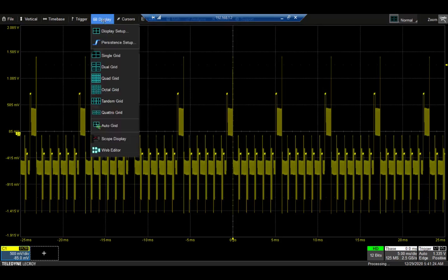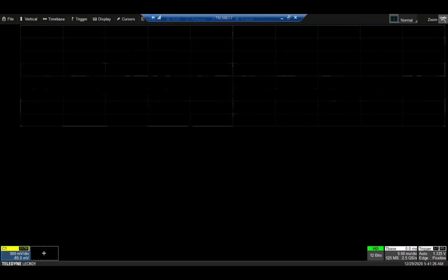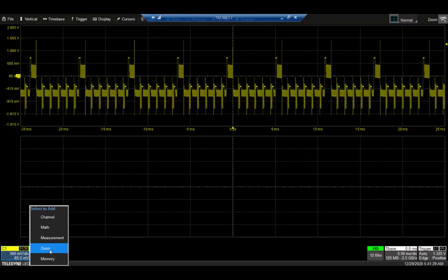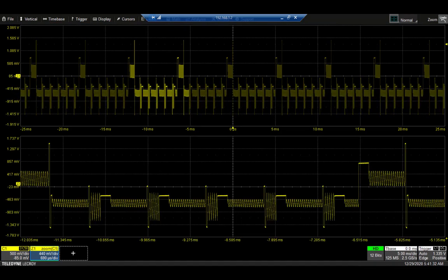And here is the new signal, visualized with the digital oscilloscope. Let's zoom in to see the details. And now I can see one cycle of the square wave. I see the signal captured using the DSO over here. Then I see the DC value, and finally the 18 repetition cycle of the sine wave. The signal that is captured by the DSO is now showing an amplitude from minus 1.5 volt to 0 volt, as we have defined in our sequencer.